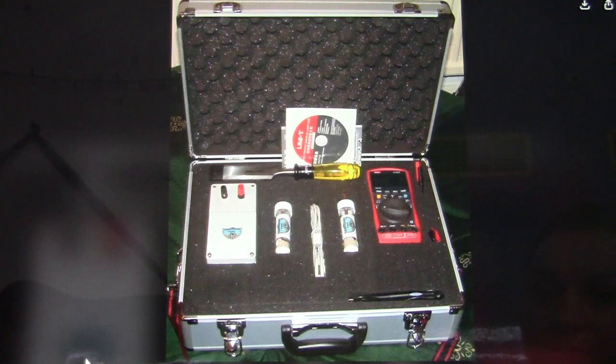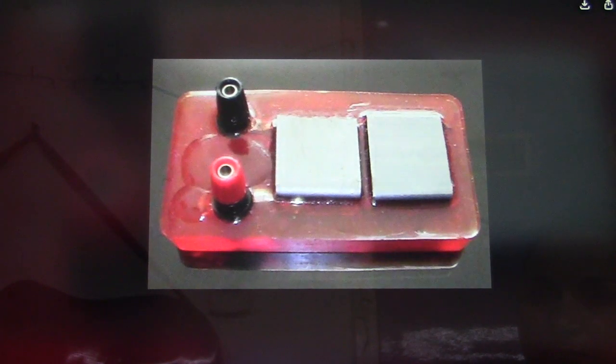Computer modelling. The Alexander cell can be simulated using software such as Excel. In these models, multiple corrosion cells interact with a cathodic protection system. By adjusting variables like transformer rectifier output, the users can observe how corrosion can be reduced or eliminated. This behaviour follows Faraday's laws, which link the amount of metal lost to the electrical current flowing through the system.